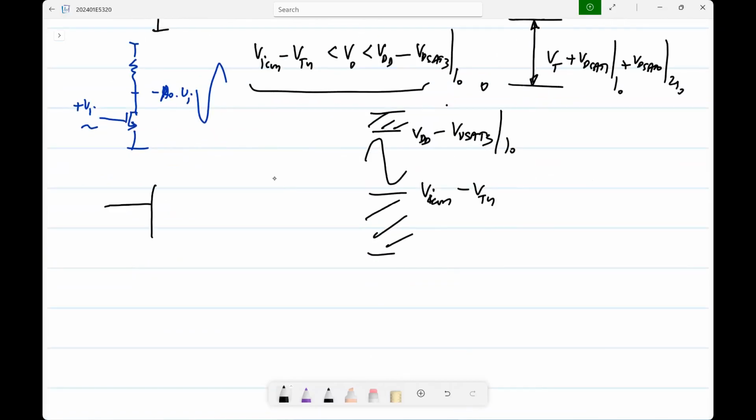So I won't go into the details now. If you have something like this, what the actual common mode voltage is depends on the circuit and what signals you apply. The swing limits give you a constraint on the signals that can be applied.